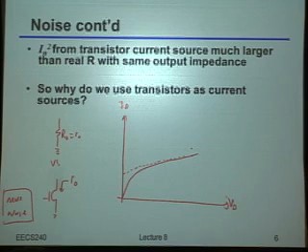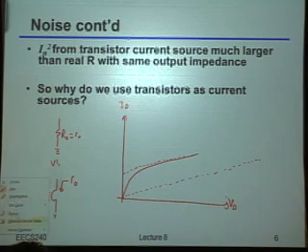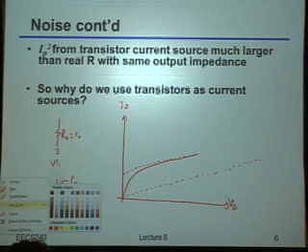Well, what I would then have to do is take that same slope, but start it from 0 voltage, right? Because it's a linear resistor. You have 0 volts. You get, well, okay, that's true for everything, but the slope is always that same slope, right? So in other words, we always have that resistance in terms of the slope between the voltage and the current. Now if you'll notice, and maybe I'll do this in a slightly different color so it's easier to see.